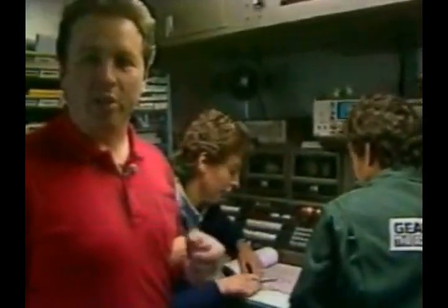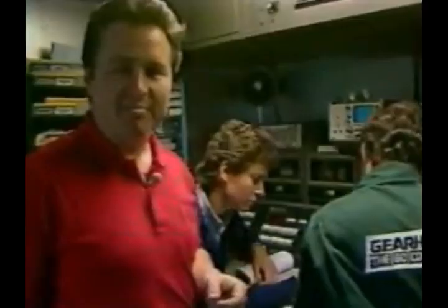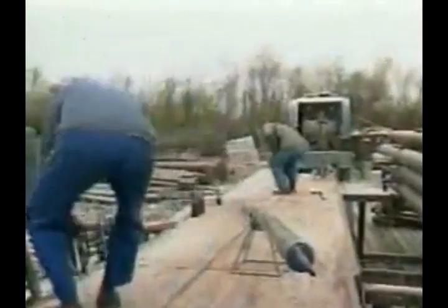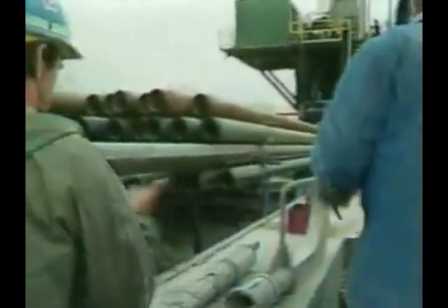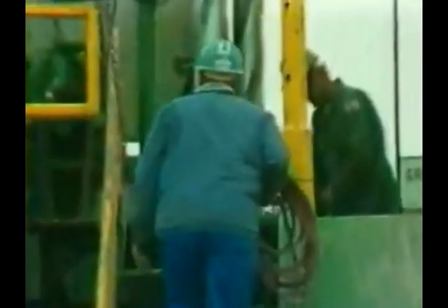When both the oil company representative and the logging engineer agree that the logs are good and any anomalous measurements are satisfactorily explained, the run is considered complete. If the logging survey consists of a single logging run, downhole logging is now complete and rigging down can begin. Sometimes several logging runs using different tools or sampling devices will be carried out during the survey. In the procedure of before-survey calibrations, proper depth recording, repeat logging, and after-survey calibrations are similarly carried out.